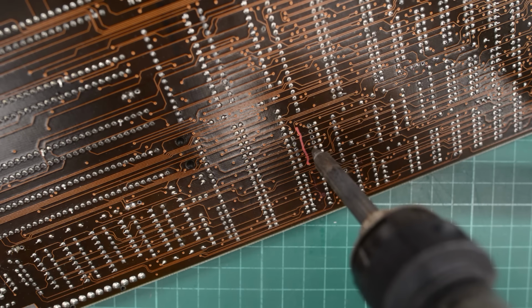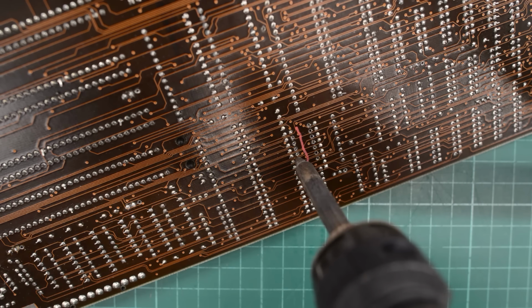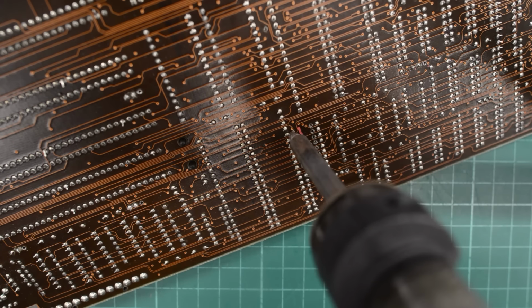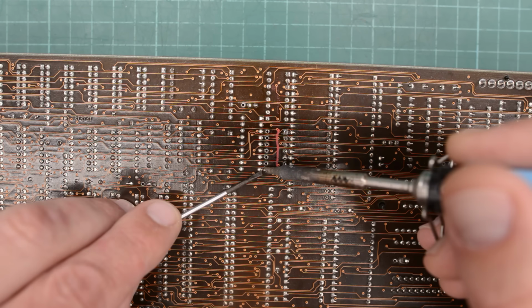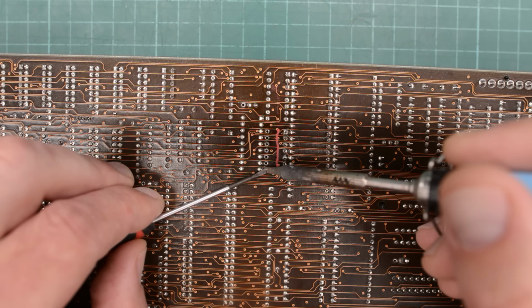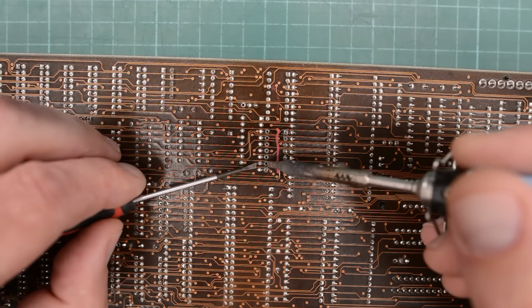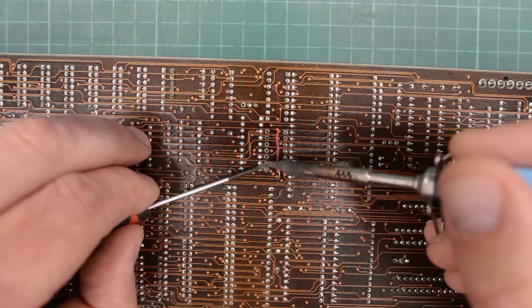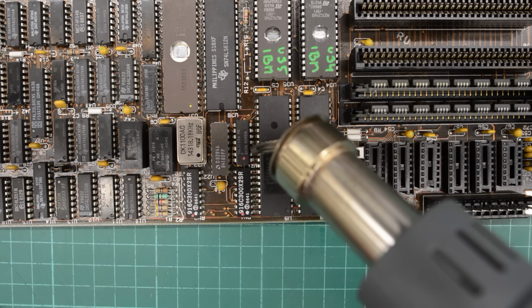It certainly did. When fresh solder is mixed with that old solder, it's much easier to clean out the through holes. Now let's get those pins unbent by heating them and then gently pushing on them. We don't want to pull that chip out with bent legs.